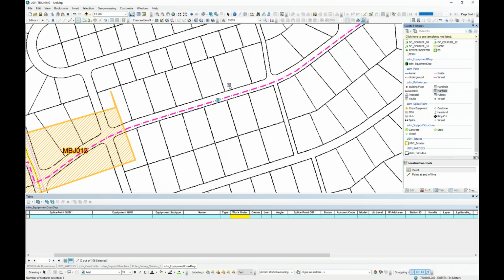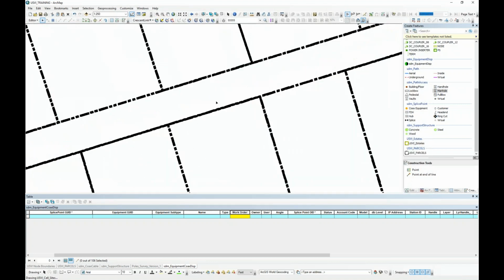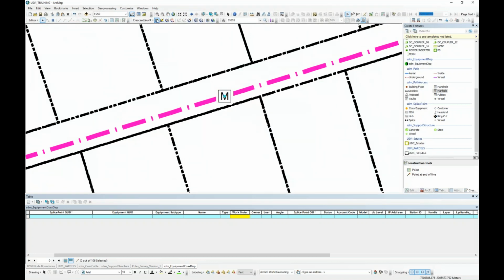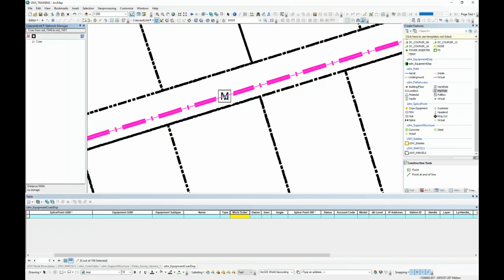Sometimes those have risers that go to a pole. We have to show all of those cables, and not cables, but the conduits that are there as well. Then we have elevations for certain customers inside their telephone room or their equipment rooms, where their backboard is, how we're coming in, whether it's from the ceiling, the floor, or the wall, however it's going to come in and tie into our equipment in relation to all the other equipment in their room.